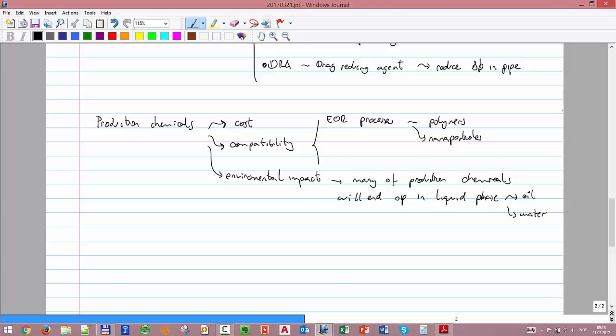That compound deposits later in the refinery, and for example plugs a heat exchanger, a pump, and then they're going to go back at you and raise you hell. What did you put in that oil? So it's not that it's problem free, it's better for the environment, but you have to be careful with the downstream user of that oil, of that crude, because it can cause some problems.